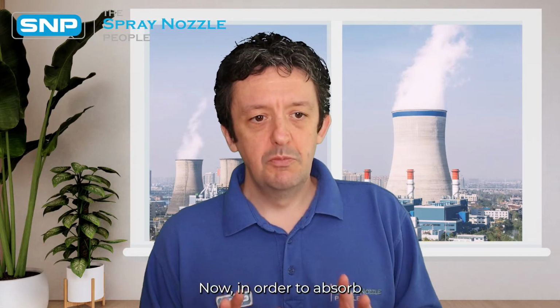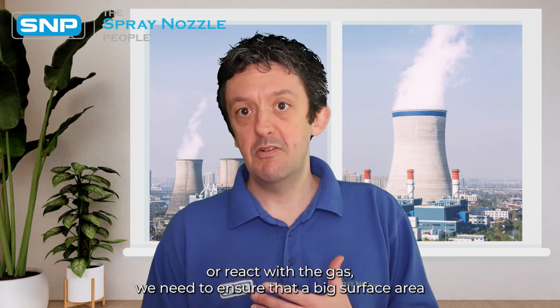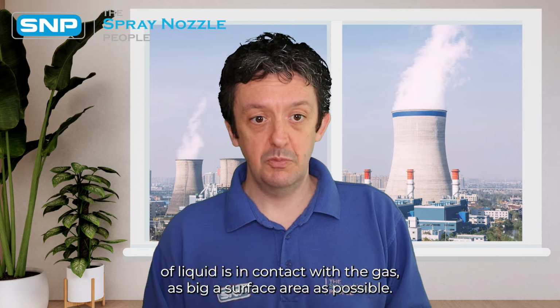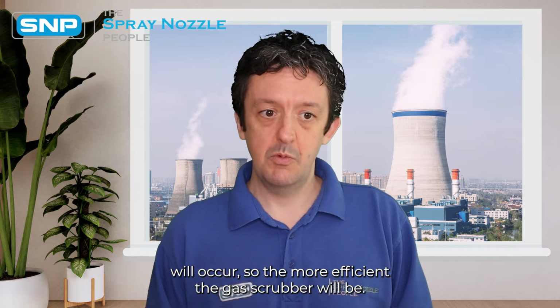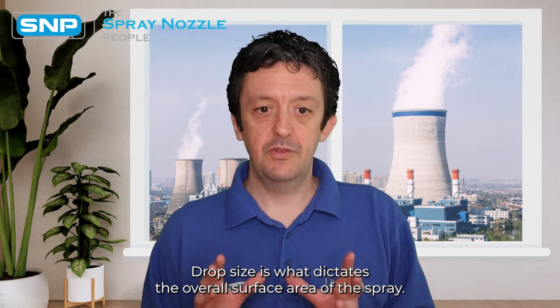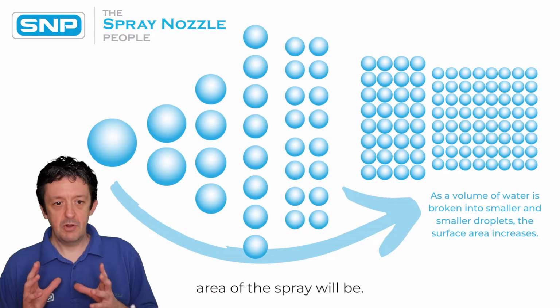Now, in order to absorb or react with the gas, we need to ensure that a big surface area of liquid is in contact with the gas, as big a surface area as possible. The larger the surface area, the more reaction or absorption will occur, so the more efficient the gas scrubber will be. Now, drop size is what dictates the overall surface area of the spray. The smaller the drop size, the bigger the overall surface area of the spray will be.